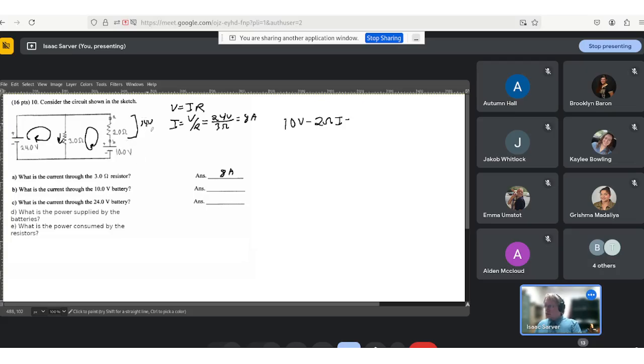My claim that this being 7 amps is not correct. So minus, that'll be 24 volts there. Good thing I did this properly with the Kirchhoff loop law rather than just going, I think it's 7 amps. I'll wager he's anticipated this.